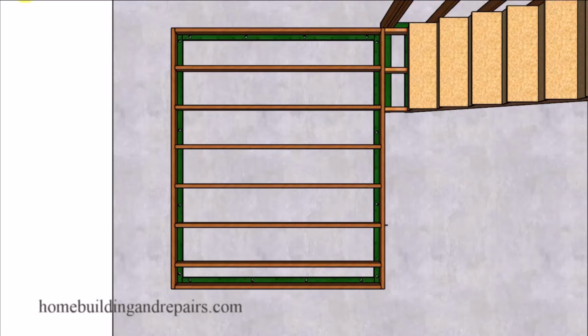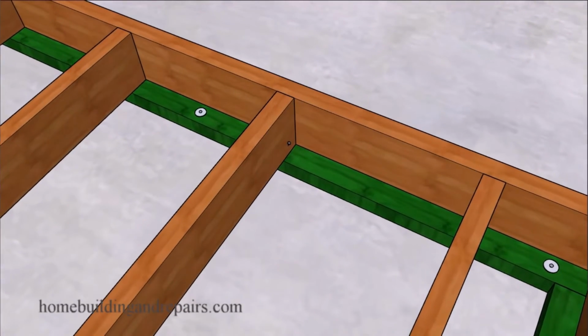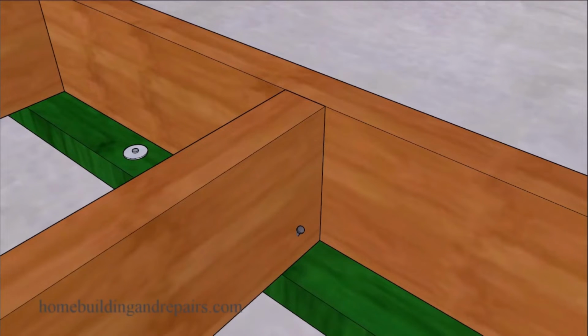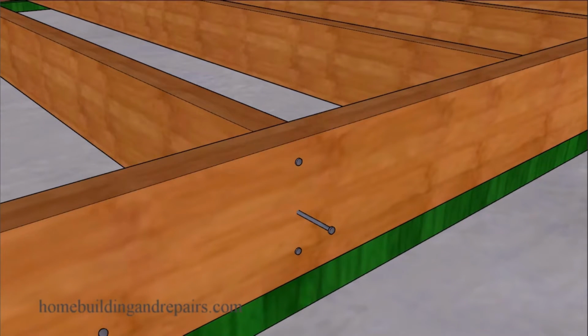So if you can avoid that, make sure that you do. And you can fasten the joist to the framing plates with a toenail or an angled nail, usually a 16D. And I will leave it up to you whether you use a common or a sinker nail. And let's not forget that you might need to check with your local building department to verify whether or not you can actually make this modification to your property, as I try to mention in most of my videos.